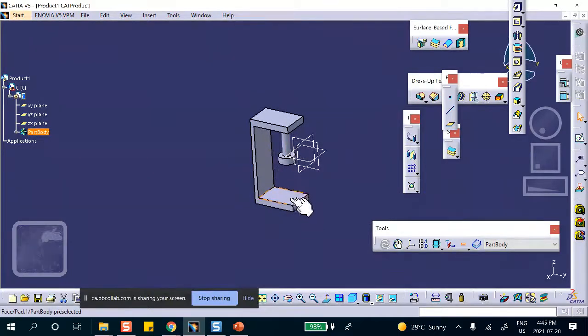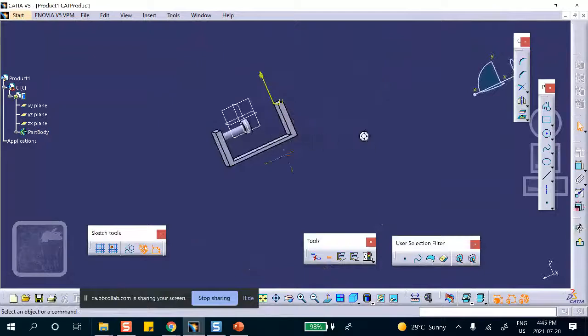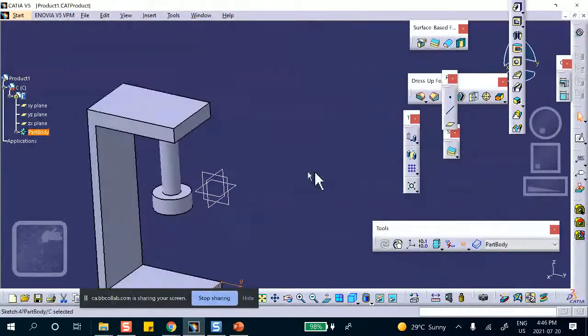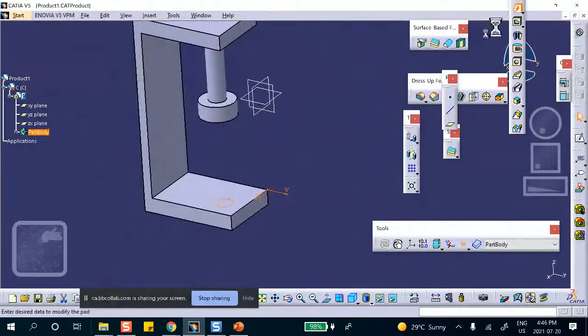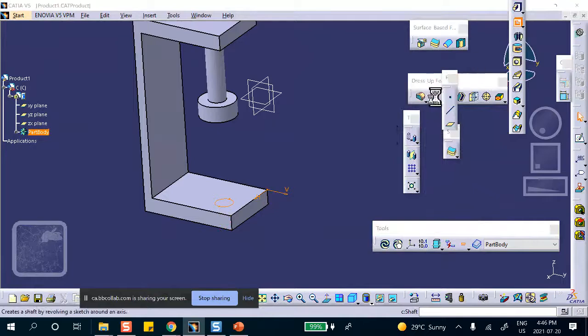Oh, I need a hole here. I need a hole because the handle is going to go through this hole. So on that face, I will sketch, project that circle. Exit, pocket it, flip. No, not pad, cancel, pocket. Good. Okay, let's go and insert the handle.